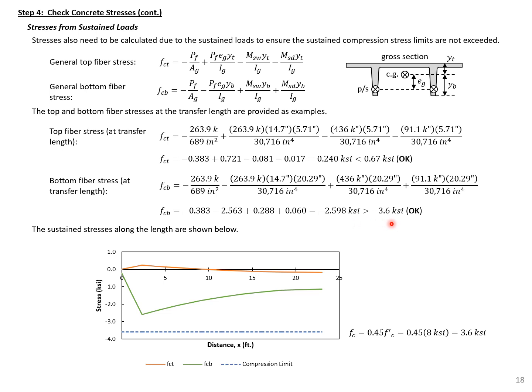We can compare that to our stress limit for our sustained load, and we can see that we're okay here. We need to check it along the length, which is what I do in this figure, and we can see that all of our compression stress stays below the compression limit as shown.